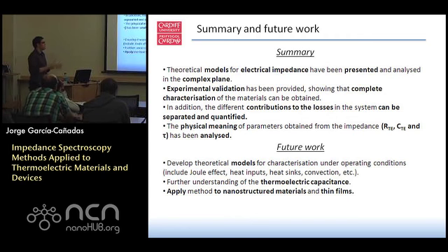There is future work going on. This is the beginning of the technique, the first models, which are quite simple. So in the future, we'll work to develop theoretical models for characterization under real operating conditions, taking into account Joule effect, heat inputs, heat sinks, convection effects, etc. And then I'm working on further understanding of the thermoelectric capacitance, what's the origin, what's the meaning. And we are also trying to apply this method to nanostructured materials and thin films.